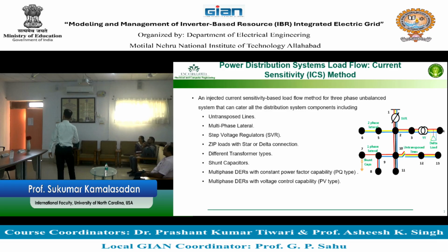The other type of inverter is basically controlling the voltage at the point by supplying reactive power. And such inverters are called PV type. Much like the reactive power that is coming from the generator.